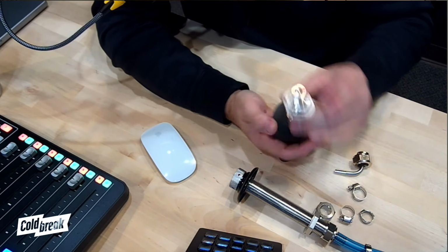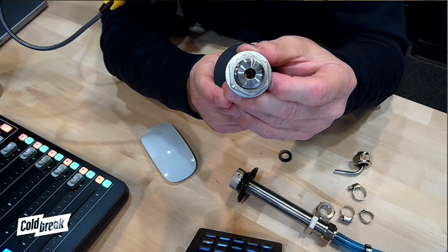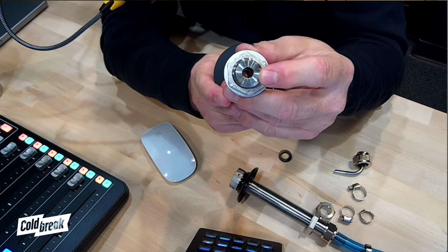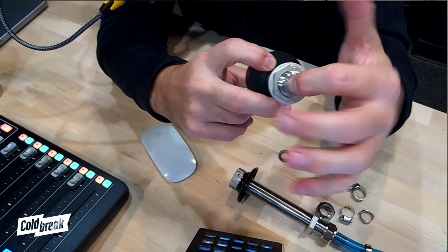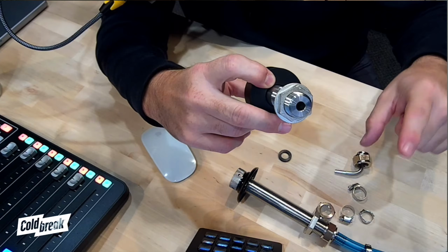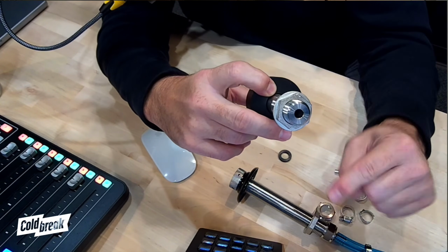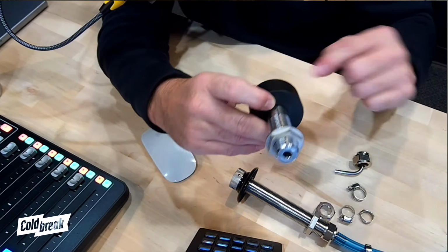And then the other big difference is if you look on the inside of it, I don't know if you can tell, but these are drilled out a little bit. So this is a 5/16 bore that goes down into a 1/4 inch bore. So our stainless steel coils will fit right inside of this shank. And then the ID never changes. So the inside of our 5/16 coils is a 1/4 inch. So your beer stays the same ID all the way until it gets to the faucet.